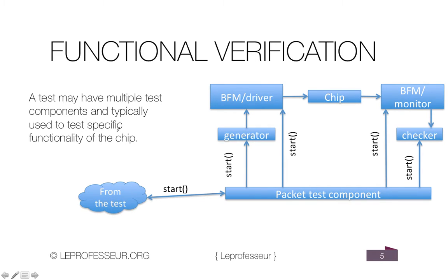tests typically check some specific functionality of the chip, say boot up sequence, for example, power on boot up sequence, right? Or say how to handle interrupts, those sorts of things, or say security. Say if your chip is implementing a security module, you may want to test whether it really works or not.